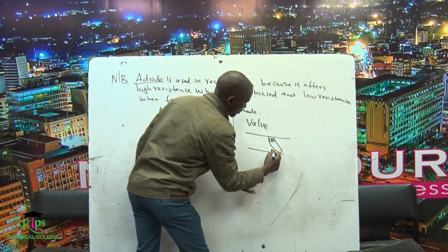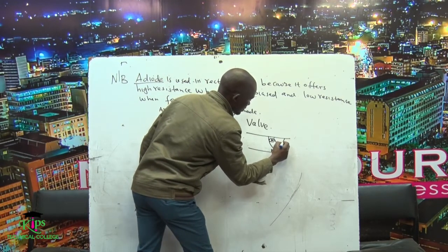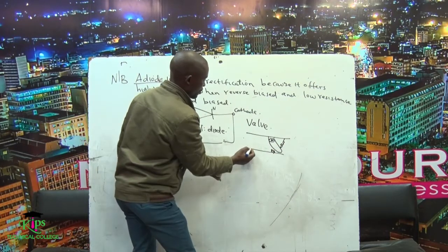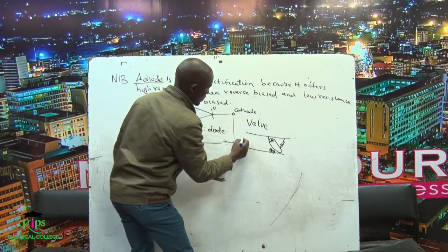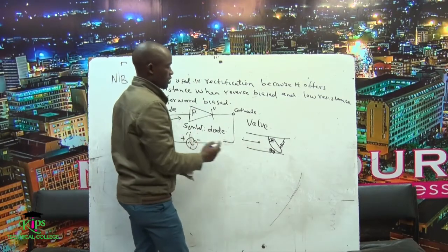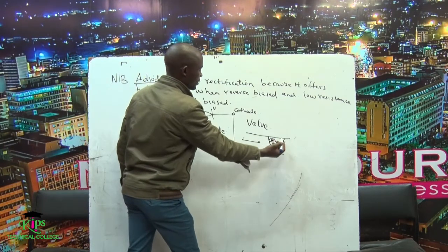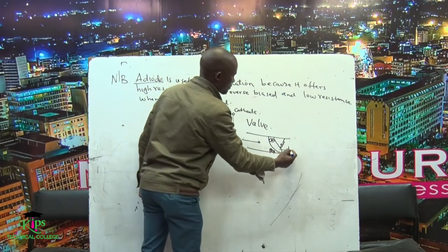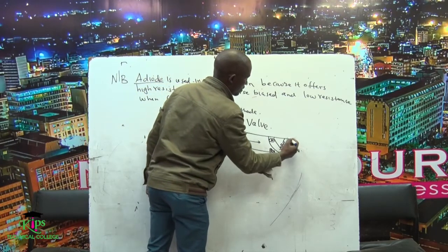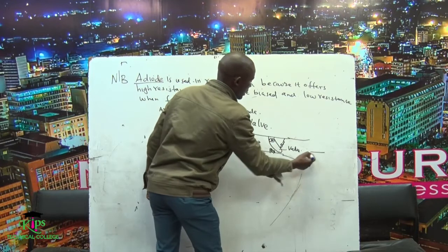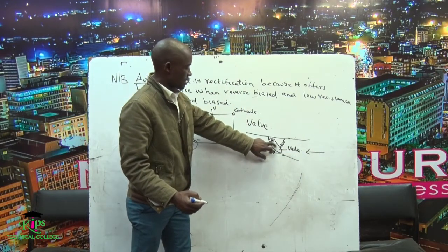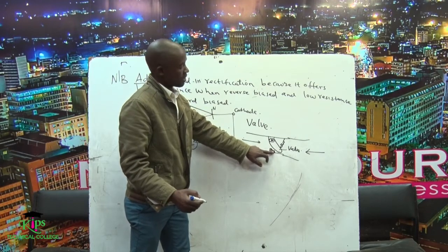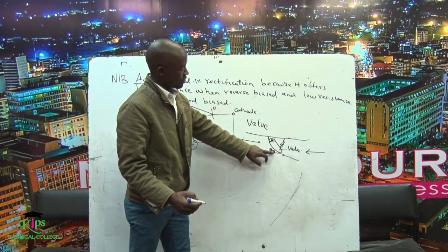We have another block there, and let us say we have a spring here. So what happens is, when water is passing in this direction, the force of the water can open this valve. But if water comes from this side, the water will be pushing this lid. It will just be lying on this one and it will not be able to open.